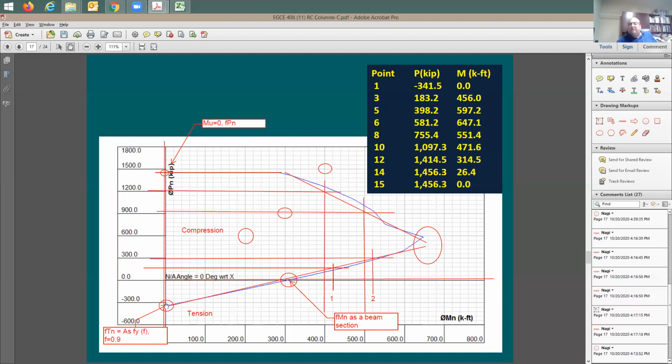It's going to be a false understanding if I tell you here that a beam supports only moment, because all beams support some moment and some axial load. But most likely, the moment is going to be the big factor. In columns, the big factor is going to be the axial load, and the moment is going to be the small factor.